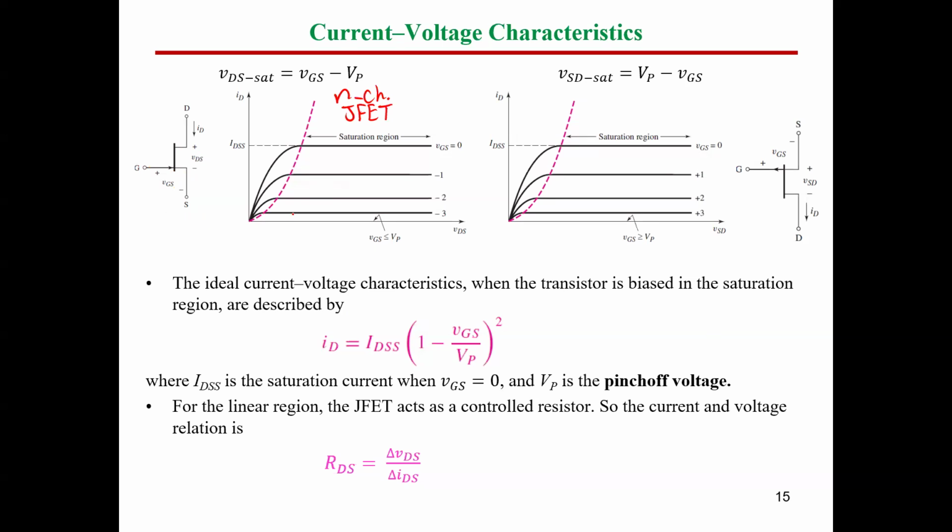And as you can see here, guys, here VGS equals 0. The more negative VGS, the less current, until having very small values here, which is VP, or the pinch-off volt. So this is now the N-channel JFET.